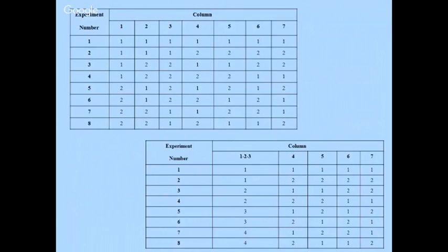This is very common in L18, because maybe some of you will be actually using it. I want to emphasize, in L18, first column is for 2 levels, second column is for 3 levels. So it is very common to merge these 2 columns and use them to conduct a 6-level factor experiment. That first column is most significant because it is on the left side, and the most significant factor you would like to study at more levels, isn't it? So this is a very, very good array for conducting your experimentation, L18.